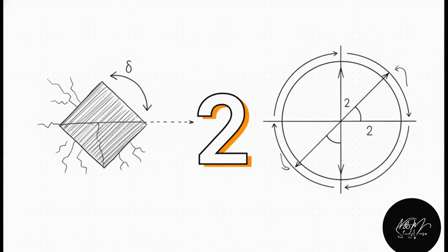Oh, and when you're using this tool, you have to remember the golden 2-to-1 rule. A physical rotation of an angle theta on your actual microscopic soil element corresponds to a rotation of 2 theta on Mohr's circle. It's this wild little quirk of geometry that perfectly maps to the real-world physics.